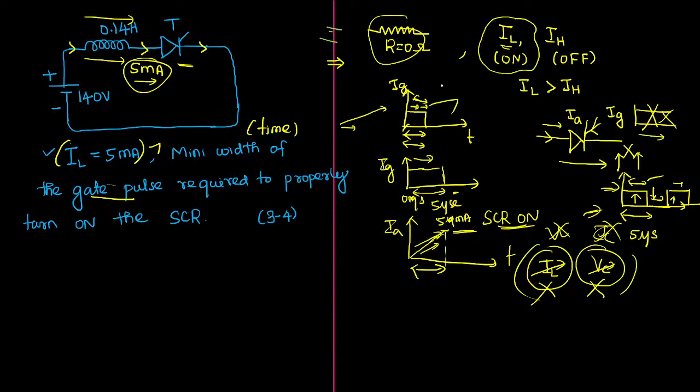No, gate current is being injected constantly. Yes, of course, I am observing that. But why is it taking a certain time period? Because it is due to the behavior of the elements that are connected in series with the SCR. Whether it is in series or parallel doesn't matter. So the time taken by the circuit to reach this latching current only depends on the parameters or elements that are connected with the SCR.